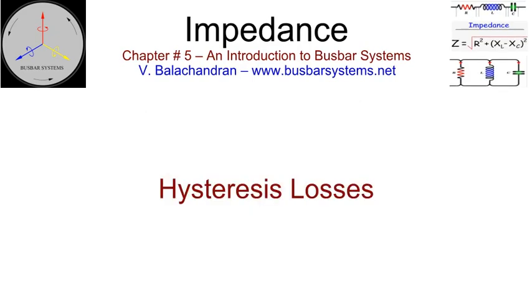Hysteresis losses. Any magnetic material in the vicinity of alternating current will generate losses due to hysteresis. This loss is caused by the magnetization and demagnetization of the magnetic material, as current flows in the forward and reverse directions. As the magnetizing force, current, increases, the magnetic flux increases. But when the magnetizing force, current, is decreased, the magnetic flux does not decrease at the same rate, but less gradually. Therefore, when the magnetizing force reaches zero, the flux density still has a positive value. For the flux density to reach zero, the magnetizing force must be applied in a negative direction.